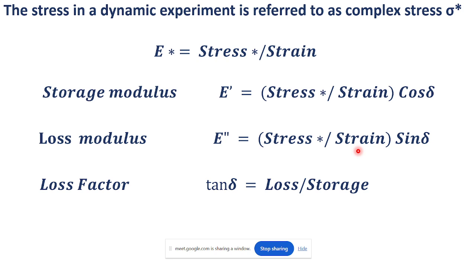For vibrational applications, I will suggest crosslink density should not be very high. If crosslink density is very high, your storage modulus will be high, so material brittleness will be higher. So it will not absorb energy. For example, we keep a table under vibration or shock absorbance type of material. In that case, the modulus is not very high. So if you increase the crosslink density, it will not absorb that vibrational energy. So it should not be a very high crosslink density.